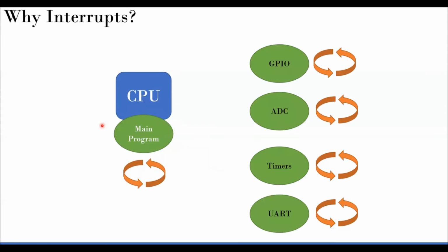Moving on. Another way to represent the whole concept I was telling: if there are no interrupts, a CPU will continue to execute a sequential main program without any interruption at all. It just does that. Then you have so many peripheral devices, so many other aspects in and around the CPU. You want to communicate to the CPU, polling is one option, which is a very trivial, tedious option. Instead of that, it's better to use something like an interrupt. So with the GPIO, when something is there, it can actually...